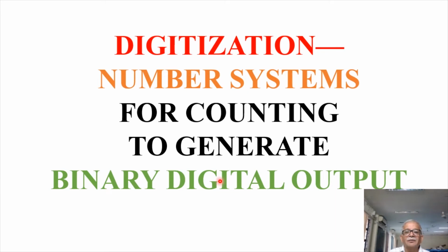We are familiar with the decimal number system where we have 10 symbols, 0 to 9, and if we want more numbers, then for the counting process we have to use a carry, so tens, hundreds, and so on and so forth. Now in the digitization process, analog voltage is converted into a digital number which is equivalent to that voltage, and for that purpose the binary digital output number has to be obtained from a given analog voltage. This process of digitization is nothing but a counting process, and for that we require digital counters and other circuitry which we will study in this talk.